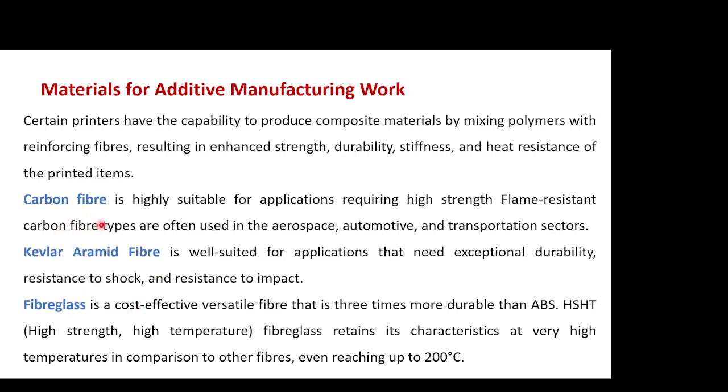While carbon fiber is highly suitable for applications requiring high strength and flame resistance, and is used in aerospace, automotive, and transportation sectors, Kevlar aramid fiber is well suited for applications that require exceptional durability, resistance to shock, and resistance to impact.